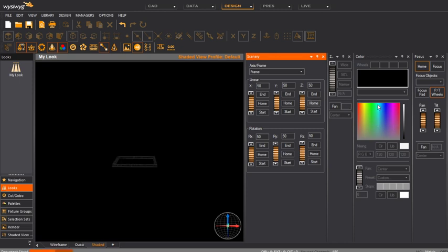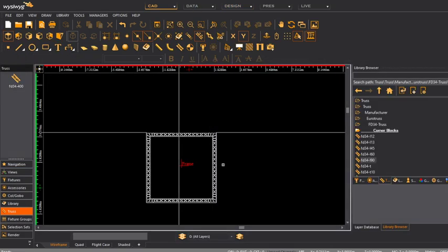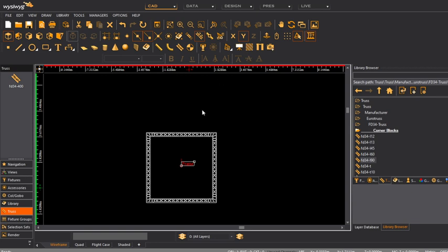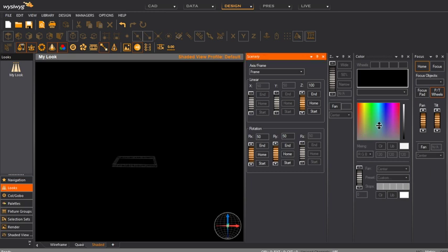So we're gonna use the C axis, and for rotation we're gonna use the X and Y. C will just rotate it. I want that. So to set up or limit your frame, you can go into the motion ranges by double clicking the frame. You can define where it should move. So let's say we go up and down 10 meters, then we go 45 degrees for rotation. Oh yeah, you're gonna set that to 0. So now it looks a bit different.